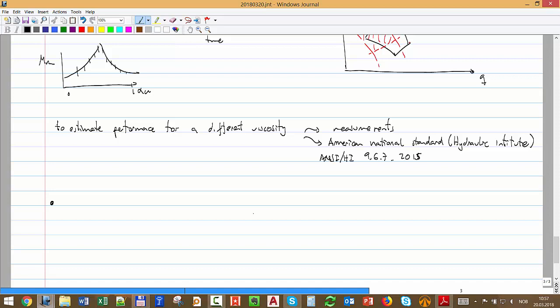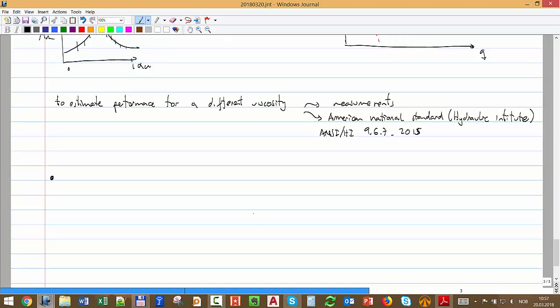Now, the one before the last thing: the pressure at the suction has to be greater than the bubble point pressure at suction temperature.